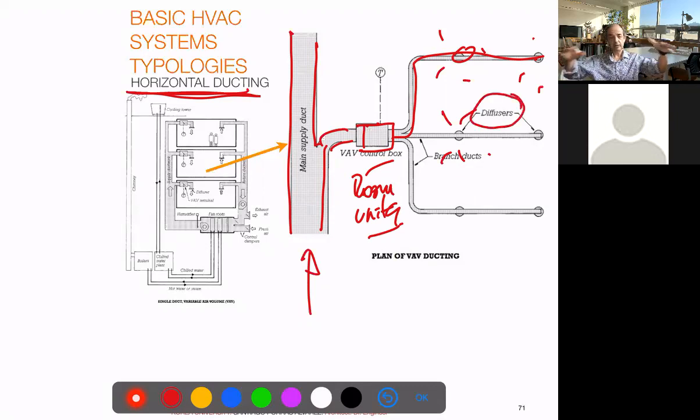So you try to make them as regular as possible, so you have hot and cold air areas, so it's much more uniform. And also you do them in a way that the air moves to the whole room and is well collected by the return shaft, without having also areas without the air moving. So that's the area which is detailed in this drawing.